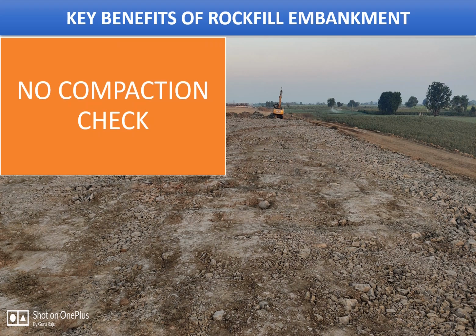Now, no compaction check is required, only the confirmation of 8 to 10 passes of vibratory rollers, and ensuring the interlocking of the aggregates by proper compaction.